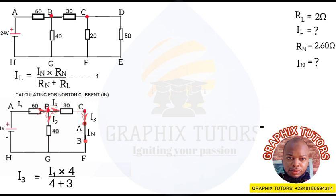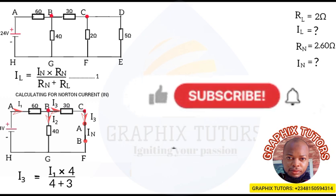I repeat, the I3 that we are looking for is equal to the total current, the current that divided into I3 and I2, multiplied by the resistor I3 is not flowing through, which is the 4 ohms, because the 4 ohms is where I2 is flowing through, all over the addition of the 2 resistors in parallel. So that's how we get our I3. That is what we call the current divider rule. So I will term that my equation 2.